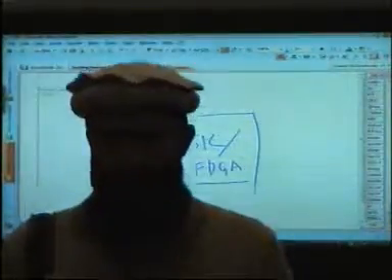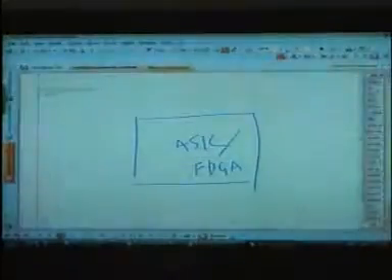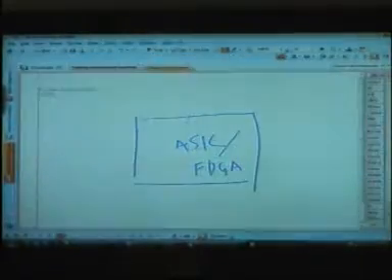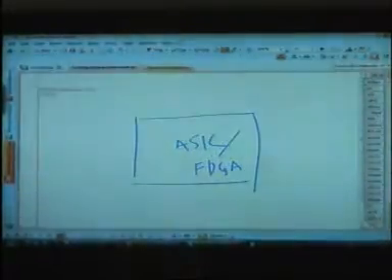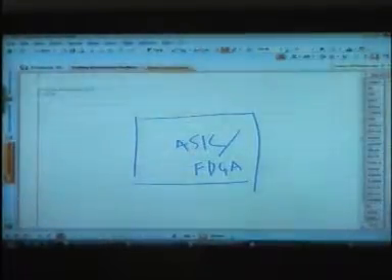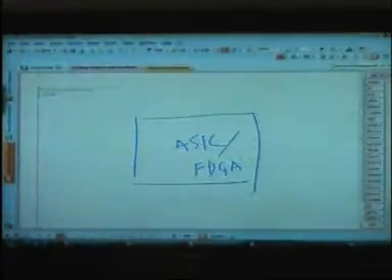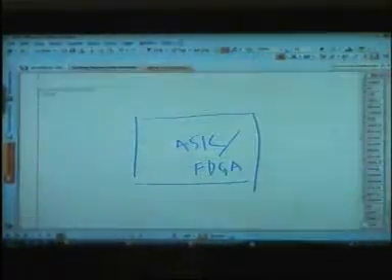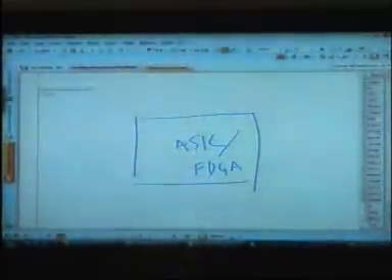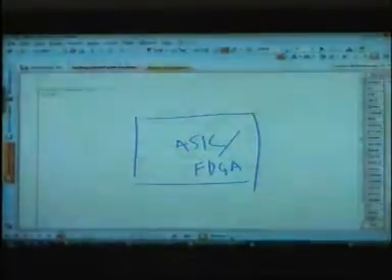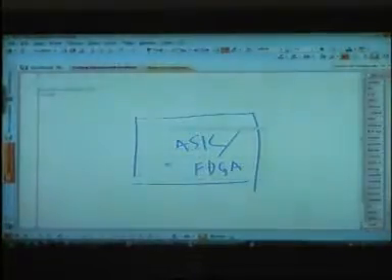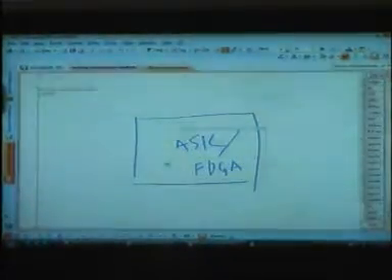But then there are ASICs. For any standard algorithm which prevails in industry, you will find there is an ASIC for it. For example, MPEG. There are MPEG ASICs, though people can do it in software, but an MPEG ASIC will be very cheap, okay? It will be very convenient, power efficient, and low in cost. There are so many reasons why it's a very natural process through which software gets into an ASIC once it is standard. So people start making an off-the-shelf component for it, right?